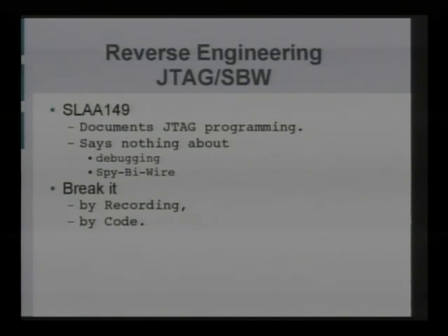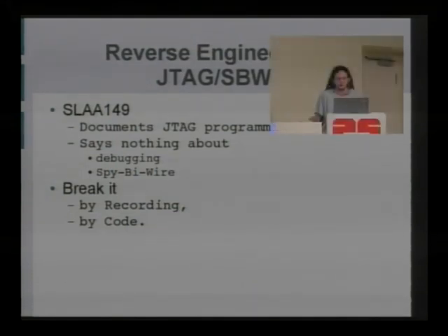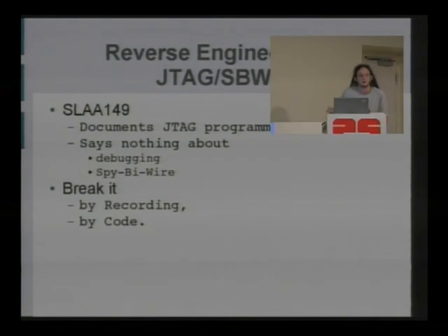As for reverse engineering JTAG, the documentation tells you how to program it, but it doesn't tell you how to debug it. You can't, by the documentation, single step the chip or set a breakpoint or do any of those things that are necessary in a proper debugger, even though the hardware supports it, even though TI's tools support it. So your only option is to use the closed source tools, a closed source proxy for GDB and such, or you can reverse engineer it.